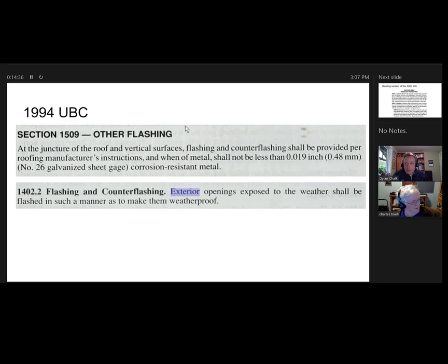Yeah. But even weatherproof can be under what conditions? Are we talking about just gravity and rain running down the side of the building? But if you're talking about sucking water into the house under negative pressure, then it starts to go uphill even. So how much does it have to lap? And all of these questions to make it truly weatherproof.